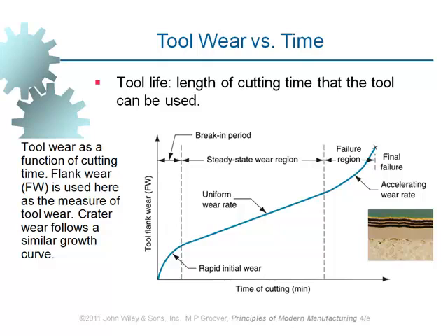Maybe you lose a part because of the bad cutting tool which has been used to make it. So we've got to replace the cutting tool before it fails, which is right at this time, somewhere here, which can be computed. When is the time to change the cutting tool? Before it fails.